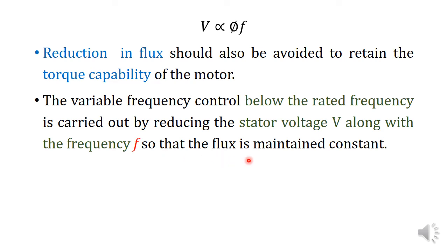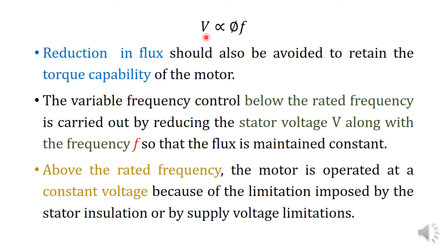But this cannot be done above rated frequency control. That means if you are increasing the frequency above rated value, then you have to increase the voltage above rated voltage. This cannot be allowed. So above rated frequency, the motor is operated at constant voltage because of the limitation imposed by the stator insulation or by supply voltage limitations.